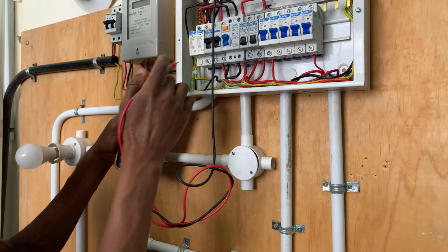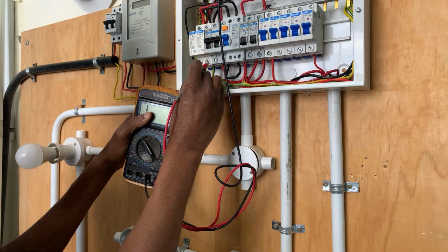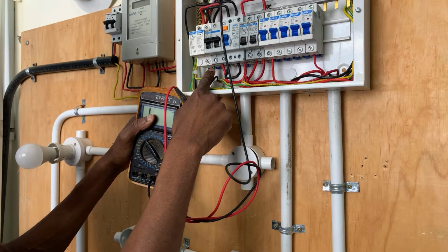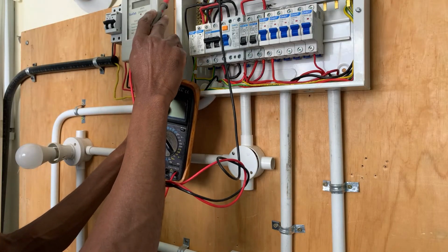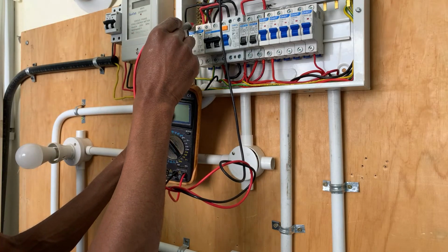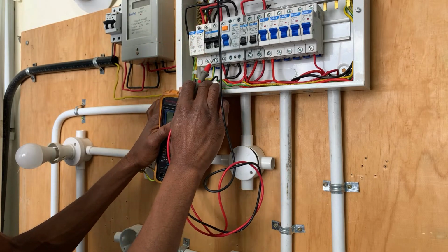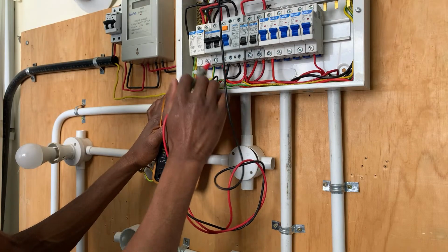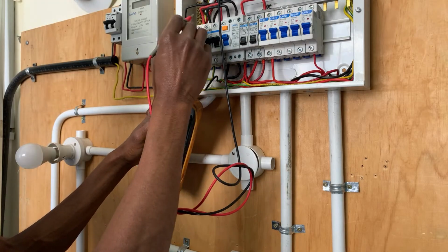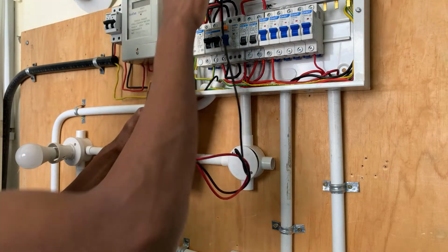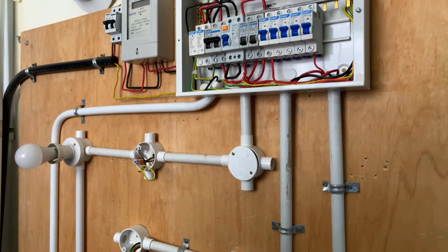Now, when it comes to our SPD, our surge protective device, you can also test it, and see that it has to be connected to the earth connection. This is where we were discussing that the incoming power, supplied by the line and the neutral, flows first to this SPD, and then it is looped, it does not flow through. But as you can see at this point, let me just have the camera closer so that you can see it clearly.